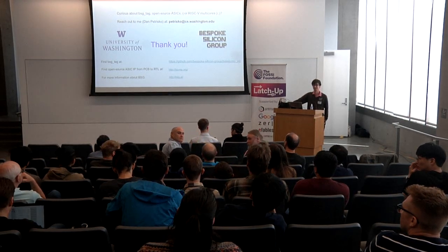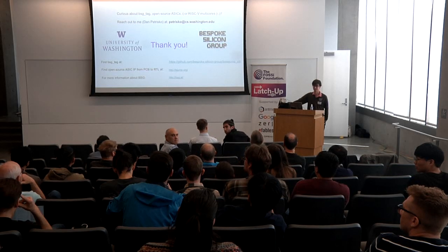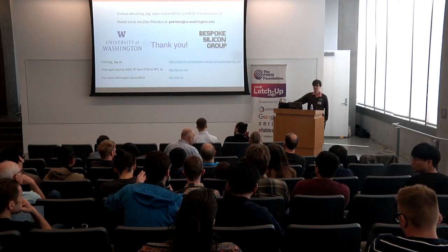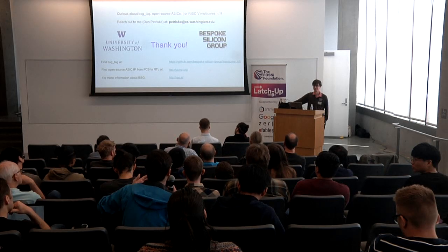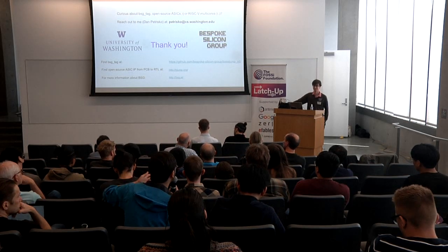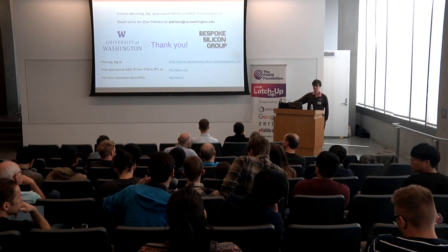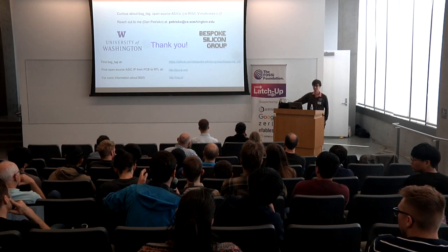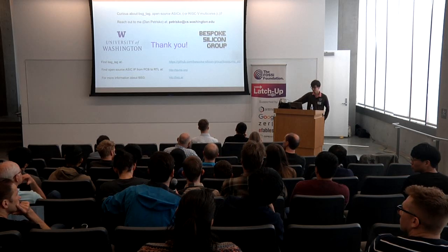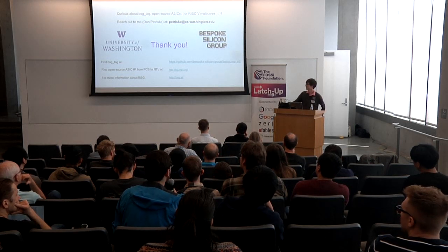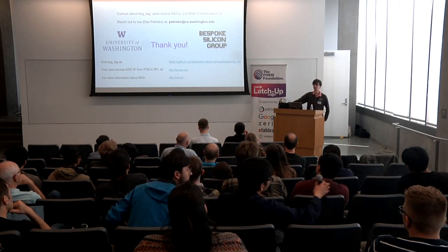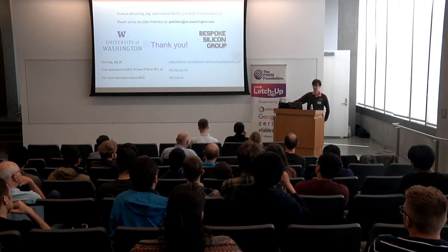So with this, you're able to send signals into the chip for bringup, but sometimes you care about what the configuration does and you want to read something out. Do you have some sort of extension so that you can read out values from that configuration bus, or do you just expect to expose more pins off your die or package to read out some signals? Yeah, that's a great question. We typically have some mechanism for out-of-band responses.